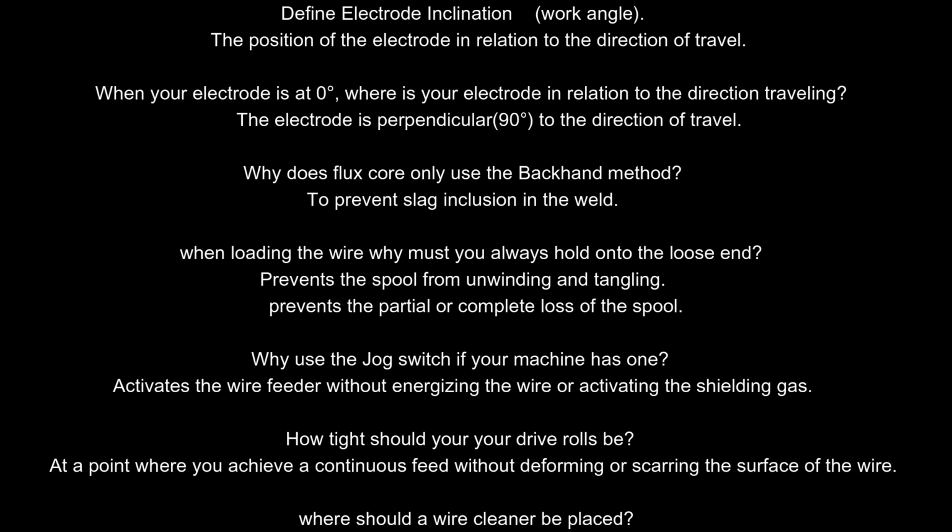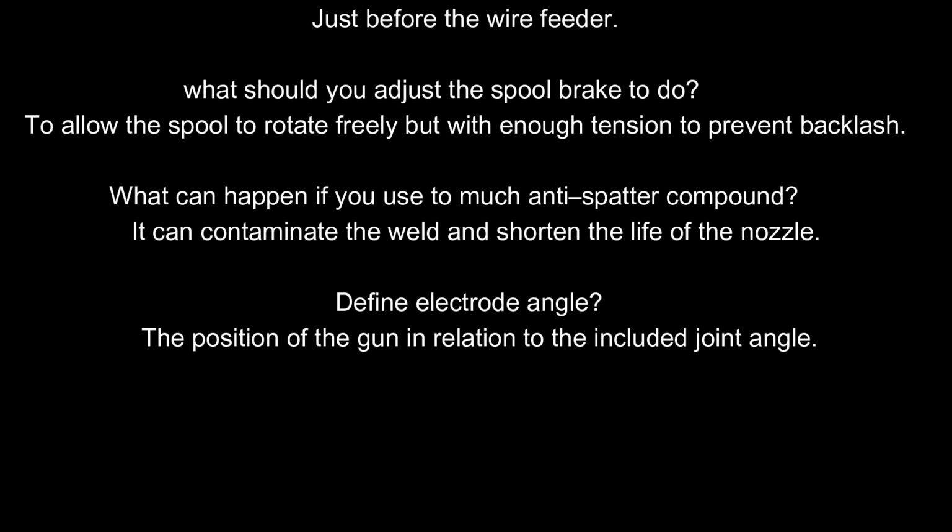Activates the wire feeder without energizing the wire, or activating the shielding gas. How tight should your drive rolls be? At a point where you achieve a continuous feed without deforming or scarring the surface of the wire. Where should a wire cleaner be placed? Just before the wire feeder.